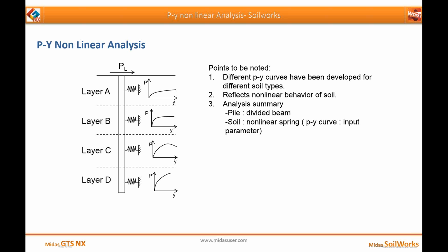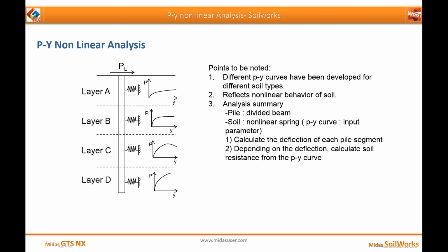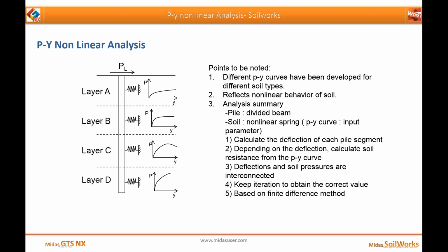nonlinearity of the spring. So first of all, when the analysis takes place, the deflection of each pile segment is calculated. Depending on the deflection, the program calculates the soil resistance from the PY curve. Deflection and soil pressures are interconnected, so the program keeps on iterating the values based on the finite difference method till it converges to a point. This is how the PY nonlinear analysis works.